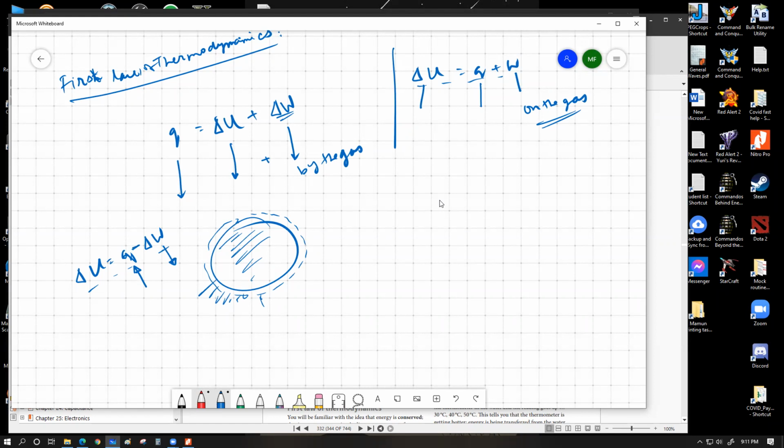If you make this minus sign plus, you can reread this as heat energy is supplied to the gas plus ΔW, which can be written as work done on the gas. So it's basically the sign of plus and minus. If you are considering this format, you have to understand that the total amount of internal energy increase can be done by two methods: heat energy supplied and also doing some physical work on the gas.